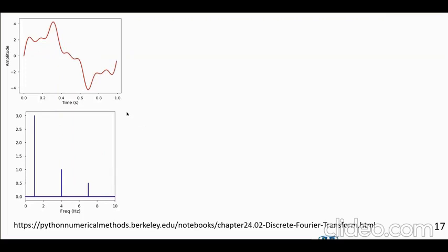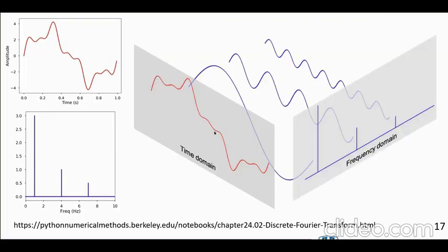Therefore, it consists of only 3 terms. Because in general, if you have a periodic function, there's an infinite number of sines and cosines. But it's kind of deceiving, because this particular periodic function is only the sum of 3 sines or cosines, depending on how things are. If you think about it, in the time domain, this curve is really made of three sinusoidal functions. One with frequency 1 hertz, the other 4 hertz, and the final one 5 hertz. If you add these up, in the time domain it looks like that.